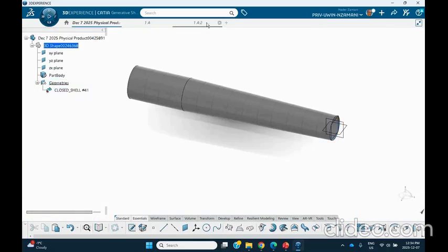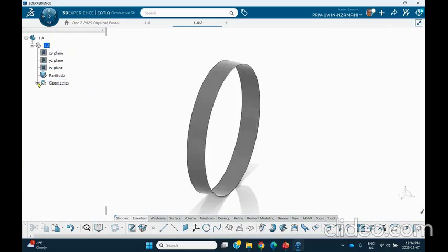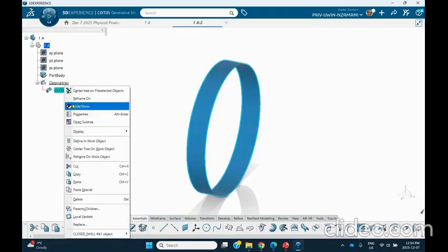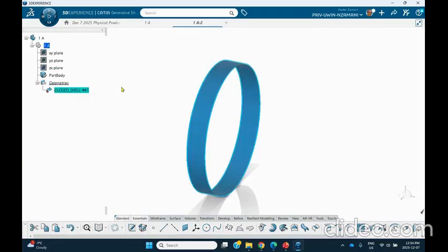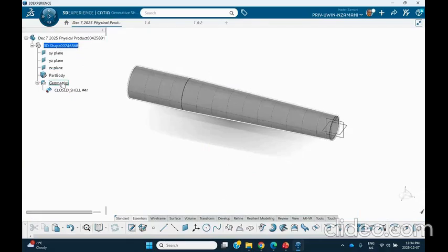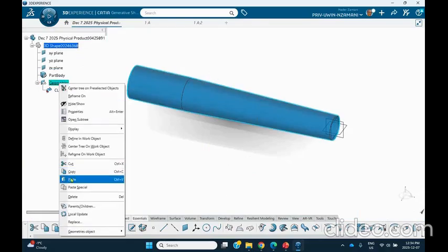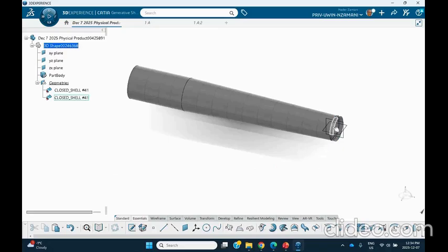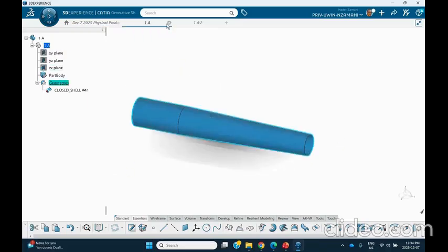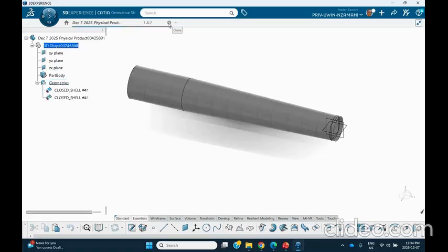And then I go to the other file and copy the surface here. Right click, copy, and go back to my original file and then save it in geometric set. Paste. There's the flange. You can see that. All right, I don't need these two other files, so let me just close them. Everything is in that file where I'm going to do all of my calculation.